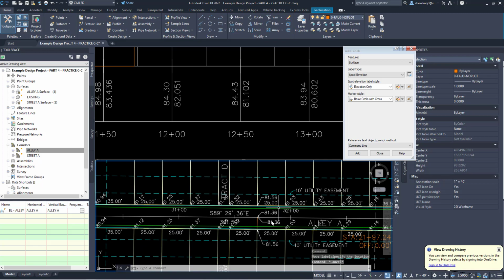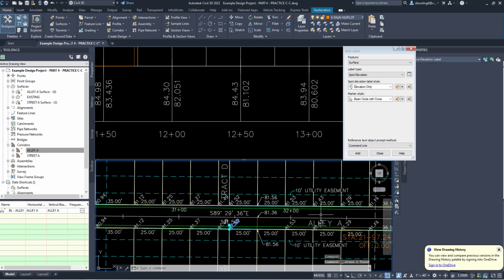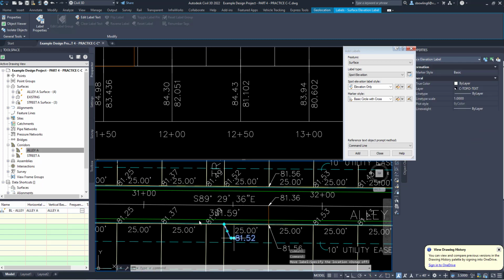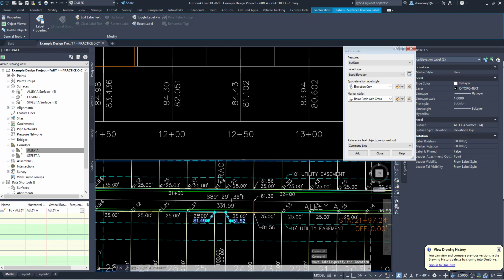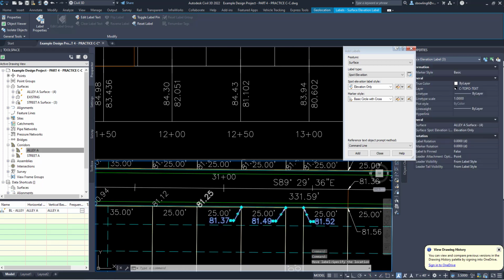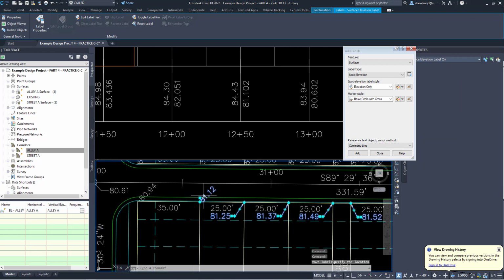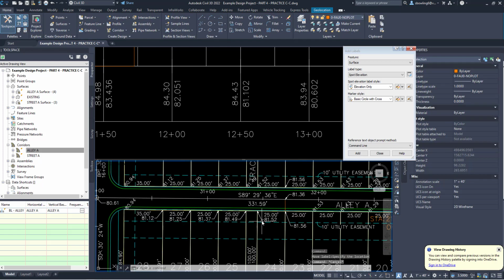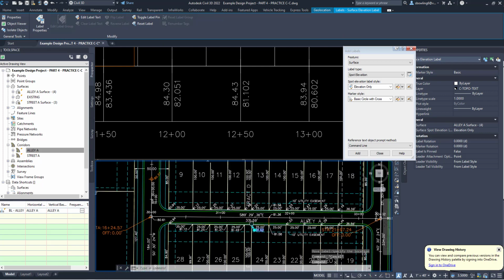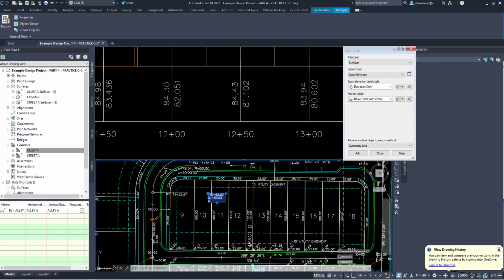All right. I don't need this one. Now you would want to go ahead so you can see these. I'm going to turn off my O-snaps and bring them down as such. Now, since each one of these has its own driveways, you would possibly need to put spot grades at every lot line. These are townhomes, so this is going to be one building, and the lot lines represent the interior building line. Okay. All right. You could also pull them down however it looks. I'm not going to worry about that right now.